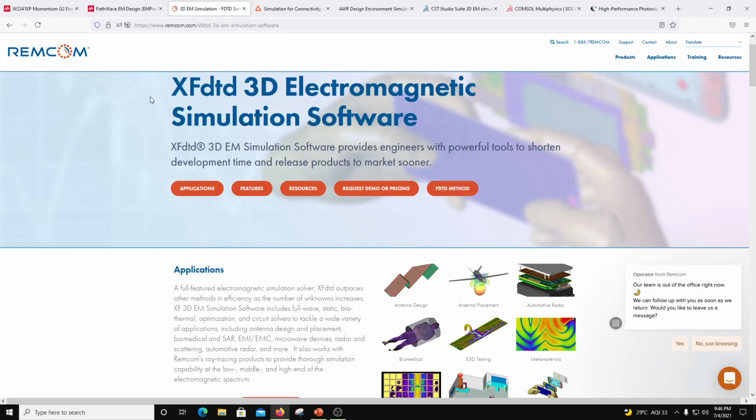So when you look at the corners of this box with the geometry inside, the corners are going to light up because there the incidence angles are different, right? So there are perfectly matched layers. There are different implementations of PML. Some of them are very good at some frequencies, some of them are not so good. So PML is that you have a box, the geometry is inside, and the box boundaries are all perfectly matched layers. Whatever is gathered by this PML is going to be transformed into your far field.